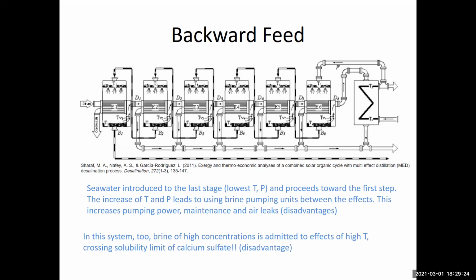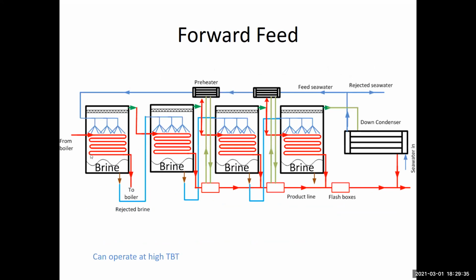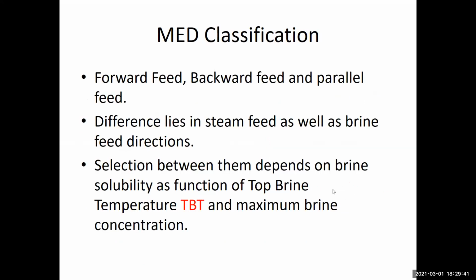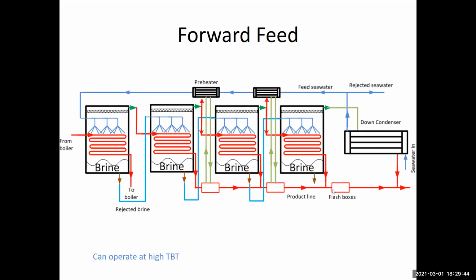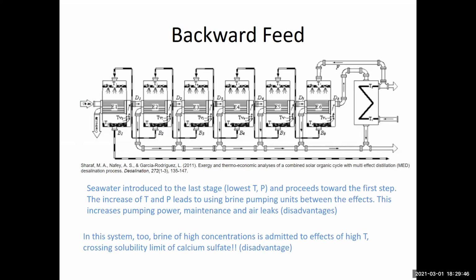Otherwise, the system is going to scale very quickly, because we are doing the combination of high salinity and high temperature at the same time. In the previous one, the salinity increases in this direction, but the temperature drops, so you are on the safe side. But here, that's not what's happening for this arrangement.